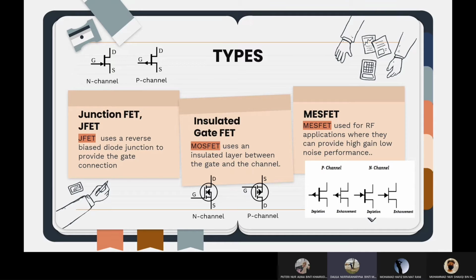The structure consists of a semiconductor channel which can be either N-type or P-type. A semiconductor diode is then fabricated onto the channel in such a way that the voltage on the diode affects the FET channel. In operation, this is reverse biased, and this means that it is effectively isolated from the channel. Only the diode reverse current can flow between the two.